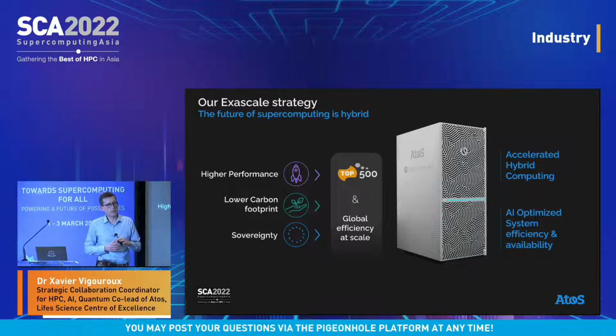Carbon footprint, just to mention that this is our fourth version of direct liquid cooling. So if you listen to carbon footprint and energy efficiency, you have heard about the PUE, the fact that when you put energy in this rack, what is the energy going through the CPU and not for the cooling? So here, there is only 1%, I would say 2% of the energy that will go to the cooling. It's only for pumps. And inside, you can put hot water up to more than 40 degrees.